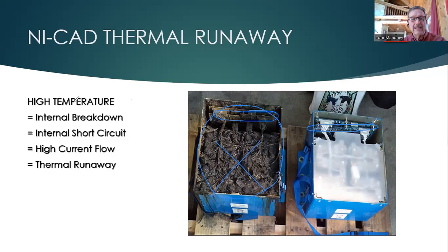So how does that happen? Well, a high temperature, the battery gets hot, then you have an internal breakdown inside the battery. Then we get an internal short circuit, and then we get a lot of high current flow. And along with all that comes a thermal runaway. Very difficult to shut that thing down. All we can do is disconnect it from the rest of our electrical usage. So not a good day if we get a thermal runaway. Not too common. They're getting better at building these kinds of batteries.